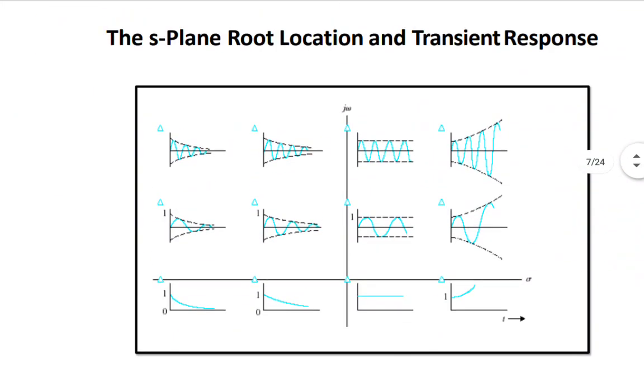Now see, in the case of Routh-Hurwitz criteria, before entering that I mentioned the stability concept, and there I told you about the S plane. S is sigma plus j omega. Sigma is along the x-axis, and plus or minus j omega is along the y-axis. I already mentioned that if all poles lie on the left half of the S plane, then the system is stable.